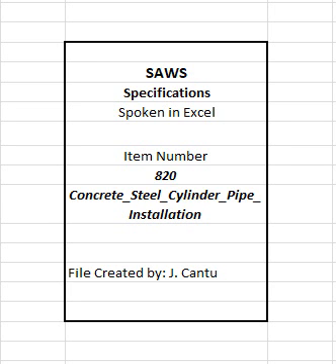24. Perform ultrasonic or X-ray testing of manual butt welds for fittings and special pipes. 25. Perform dye penetration testing of manual lap welds for fittings and special pipes and for joint ring weld onto cylinder.